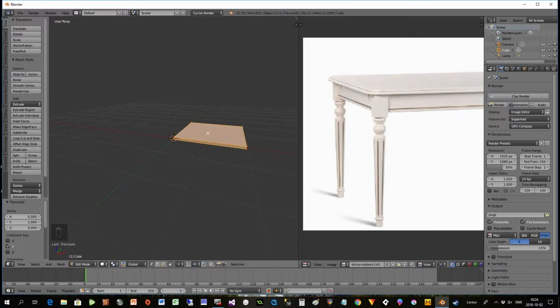Before I add the mirror modifier, I need to avoid my first trap, and that is I cannot keep the faces where the mirror modifier meets, because in that case it will destroy when you do subdivision and so on. So those two need to go.